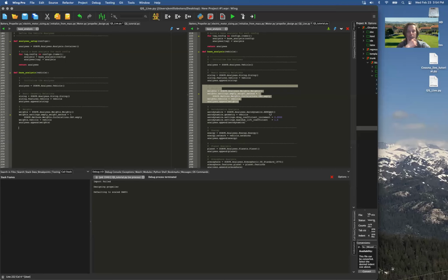If you try to use, for example, vortex lattice, it will obviously not be a stalled vehicle because it does not have viscous effects or anything like that. So the lift will just be linear. You won't actually see the change to the drag regime. So this is a simple model that basically takes the airfoils and makes some assumptions.